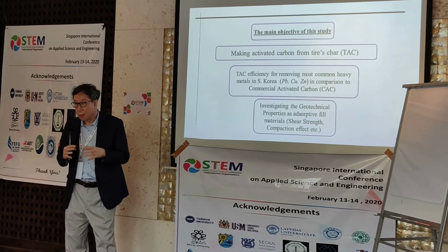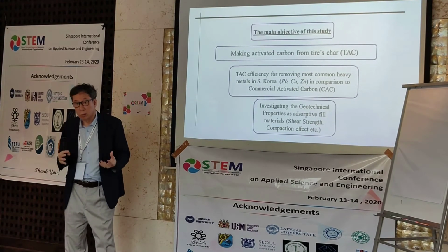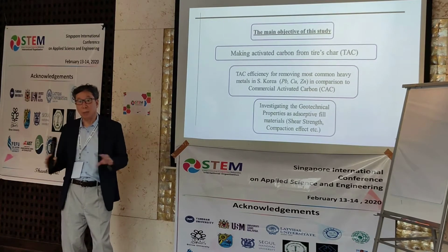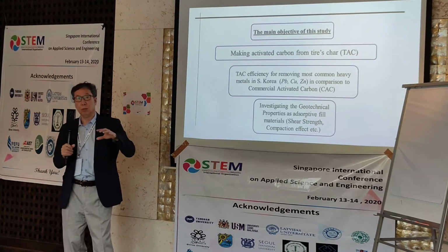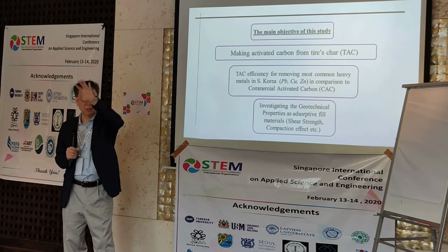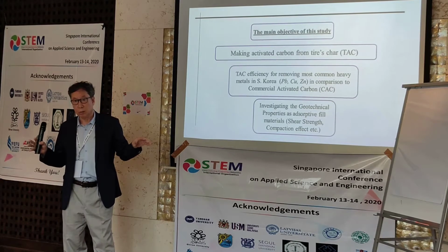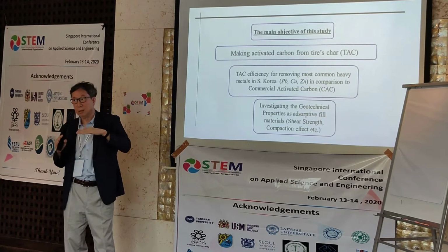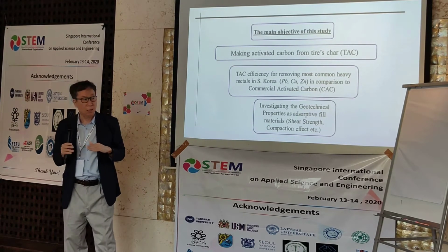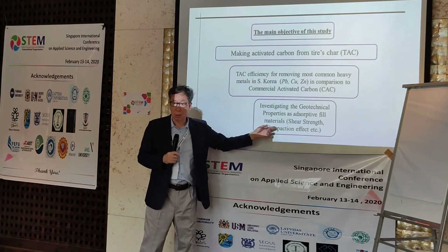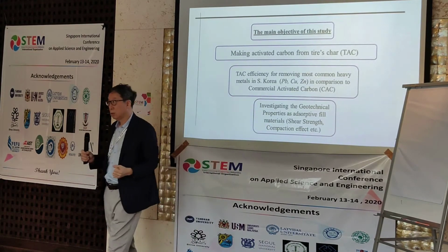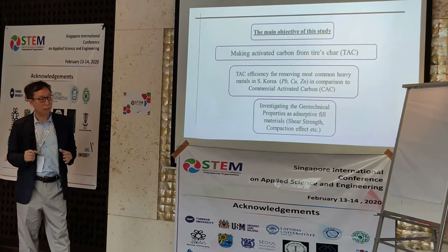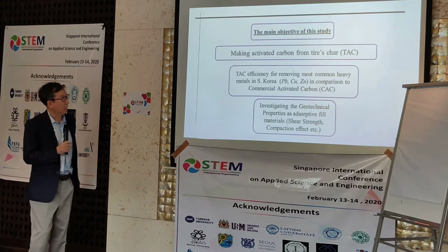I try to mix those materials with the local soil. Then it should have good engineering properties as a foundation bearing material, because we have to build some industrial facilities above the soil zones, so it should have good bearing capacity against settlement and against shear strength. So even when we mix in the tire material, it should show good engineering capacity against settlement as well as absorptive capacity. Next.